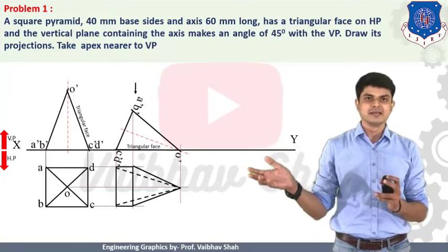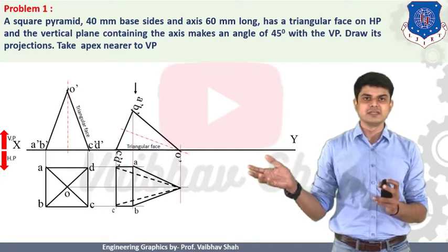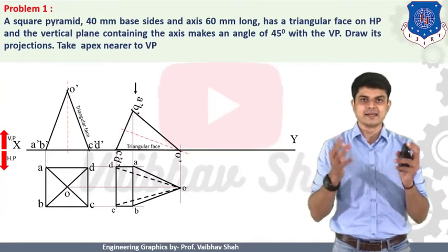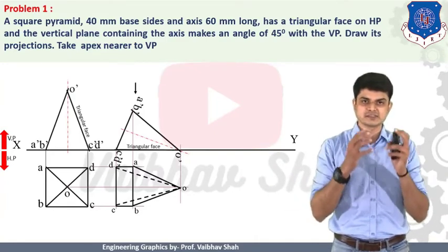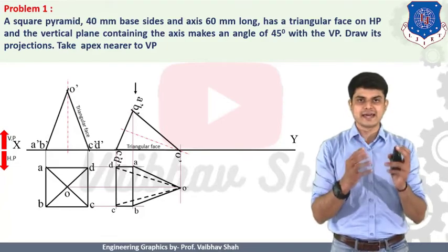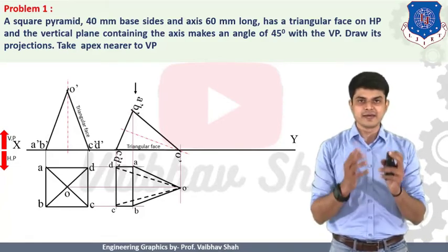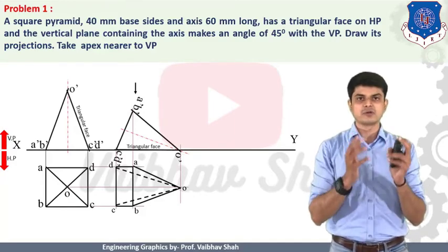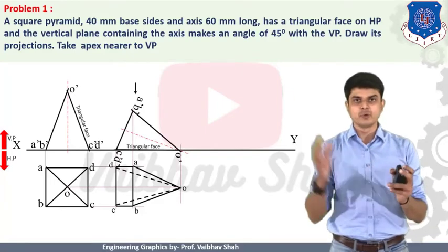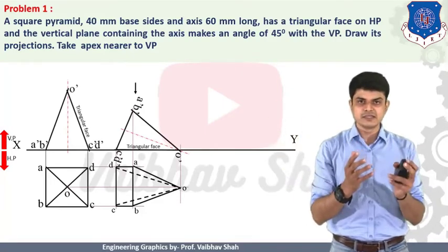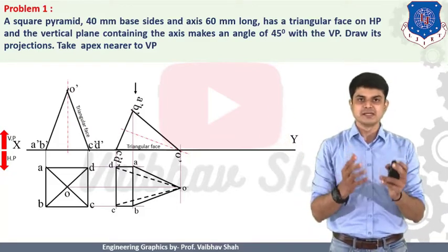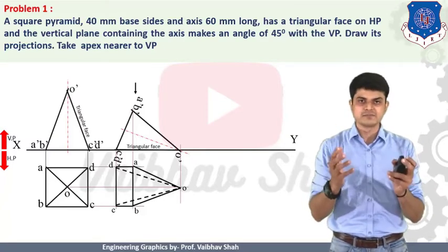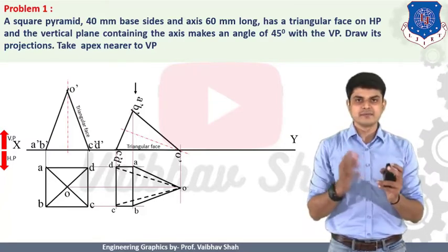We will be drawing this line in such a way that it is a hidden line in our case. So here your lines O dash, C dash and O dash, D dash are hidden lines, but your line C dash, D dash is not hidden because it is a line on the outer periphery of an object, and whenever there is any line on the outer periphery of an object, it must not be dotted or hidden. And secondly, when you are looking from the top, you can obviously see the C dash, D dash point. That means the line constructed by C dash, D dash is obviously seen when you are looking from the top. So that means we should construct this line like this.